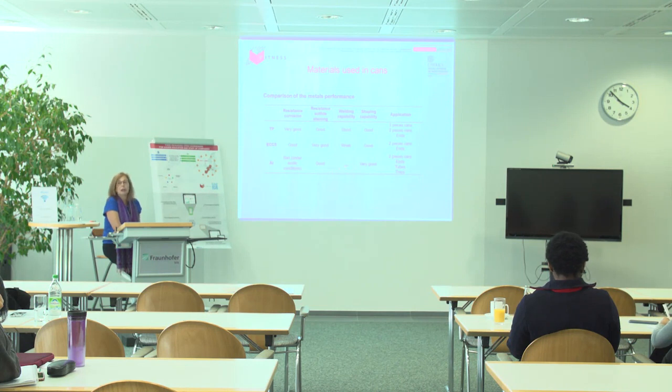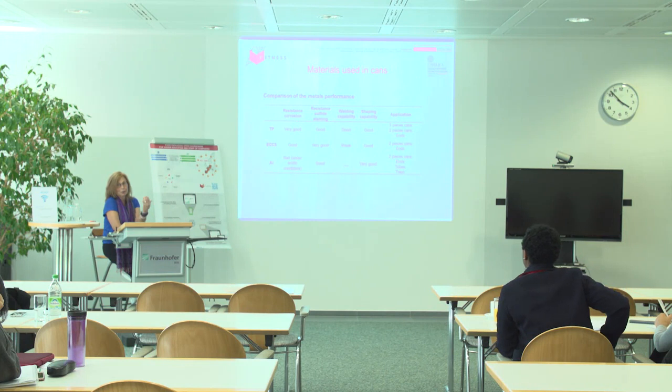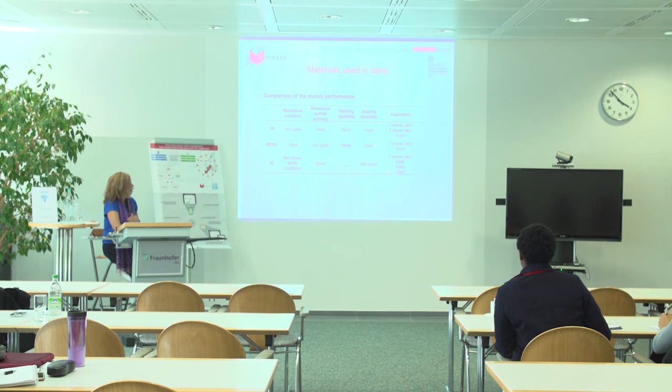So aluminum is never used for 3 pieces cans, because we cannot weld to produce the body. So aluminum is only used for 2-piece cans. For ends, for lids, for tubes, for trays, aluminum can be used.